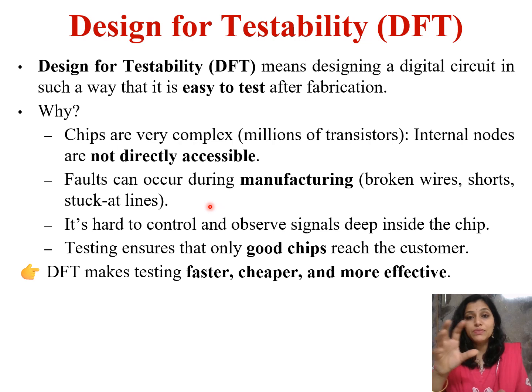But what about the gates or transistors present at the center? For that, we must design our circuit in such a way that observability is maximum and controllability is maximum. Observability means ability to observe each and every node in the chip, and controllability means ability to control them, or set them to 1 or 0.